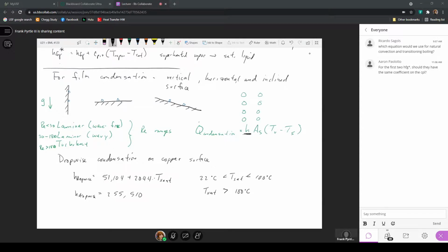And that's because, again, this expression for the condensation means that there's a phase change that is actually occurring, in that we're removing heat from the vapor primarily by that phase change that's occurring in the vapor so that it becomes a liquid. So whether we're boiling water or condensing water, we get extremely high heat transfer rates for relatively low temperature differences